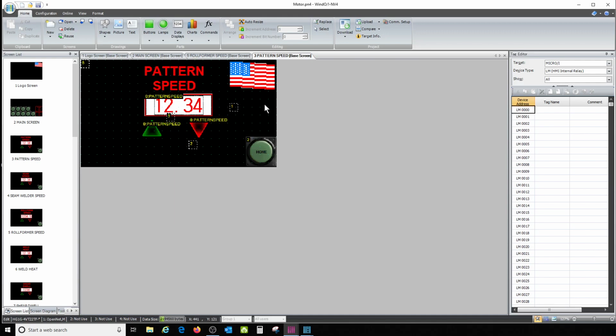Okay, we'll go into that here in a minute. I'm going to actually do a short program, and we'll wind up, hopefully sometime in the near future, I'll get it to where I can put it on my actual PLC in here and video it, and I'll show you how to make the analog go up and down on it and show you it actually working. I don't have a VFD, unfortunately, but I do have an analog meter, a 4 to 20 meter we can put on there, show 4 to 20 milliamps, and we can see it that way. Anyway, that's that one. I'll make that available, like I say.